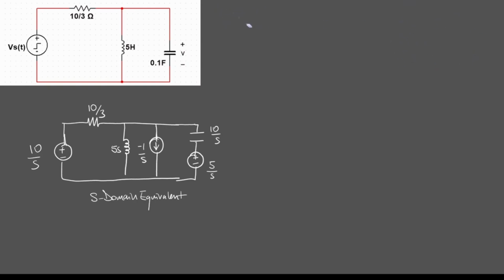And the pro tip we can see here is that since we have a couple of elements in parallel, you can see 1, 2, 3 in parallel, and this is simply a voltage source then a load, we can use nodal analysis, we can use KCL.